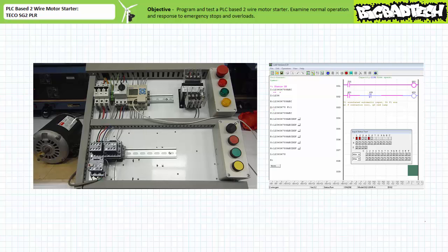You'll note the red pilot lamp briefly blinks on, indicating there's a fleeting moment of time where output Q1 is asserted and the F contactor hasn't fully closed. Once the F contactor fully closes, the contradiction resolves itself and the red lamp turns off. When the selector switch on input 1 is reopened, the F contactor coil is de-energized, the F primary contacts open, and the motor turns off. The system behaves as anticipated for normal operation.